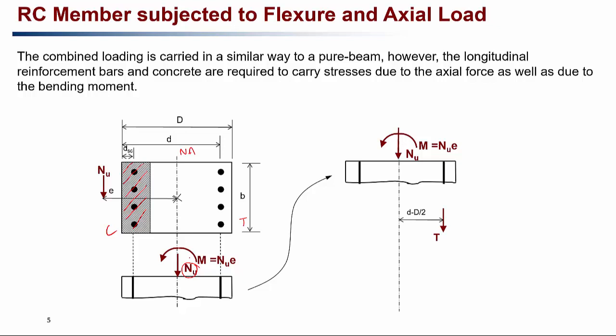Now, as described earlier, the steel in here will take the tensile force. That means the steel here is taking the tensile force T, and this steel is at the effective depth of d if we consider from the topmost compressive fiber. So the depth up to the center of the reinforcement, as we did for the beam, is small d, which is effective depth. Now in the compression block, as you can see here, this is taking the compressive stress. So here we have the compressive stress acting in the concrete block, and the total compressive force taken by the concrete block is denoted by Cc.